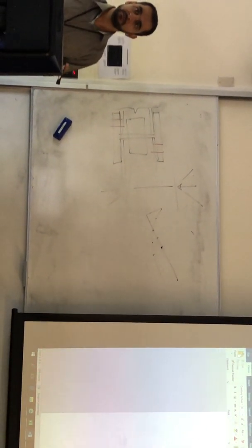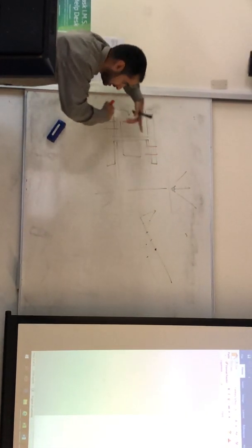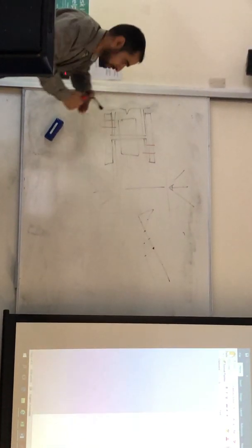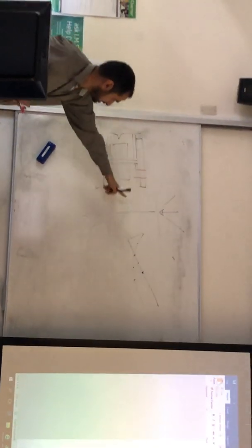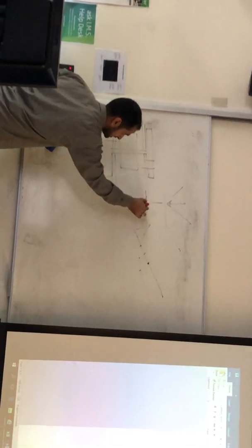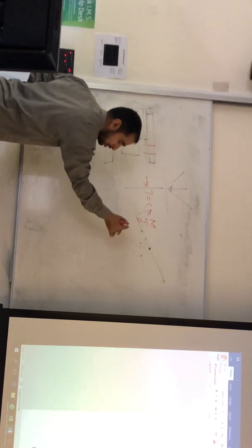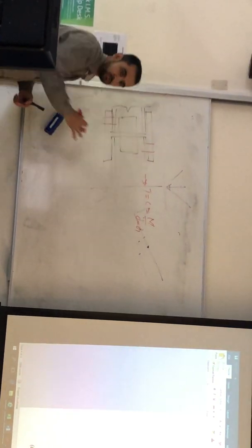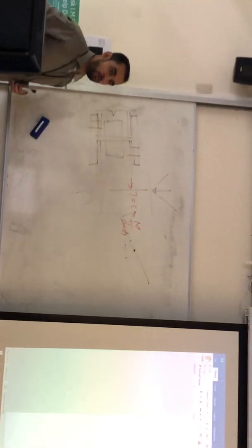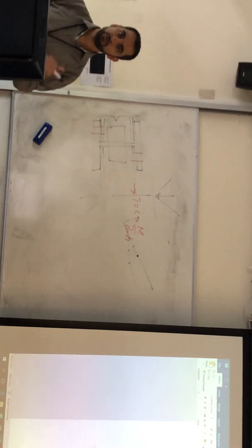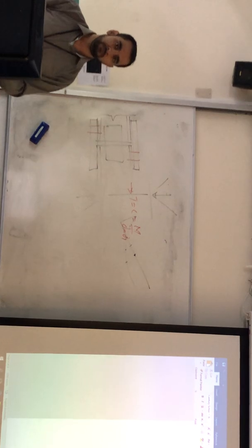What type of force is it? Shear failure. If I'm trying to load that bolt, it's shear. So how many bolts do you have? 4, 6, 8, 10, 12. The tension that you have in here, tension or compression, is equal to M divided by D, and D is equal to D1, which is center to center of the flange. That's it. Then after that, from the bolt, where does the force go? To the plate, right? In the plate, what type of failure mechanism is it?